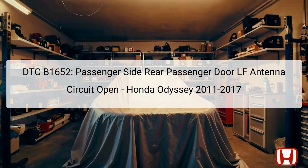The DTC B1652 relates to an open circuit in the passenger side rear door's LF antenna. This issue primarily influences the operation of the keyless entry system integrated into the vehicle. The LF antenna, located at the outer handle of the right sliding door, plays a crucial role in receiving signals from the key fob, enabling functions such as unlocking the doors and starting the engine with a push button.